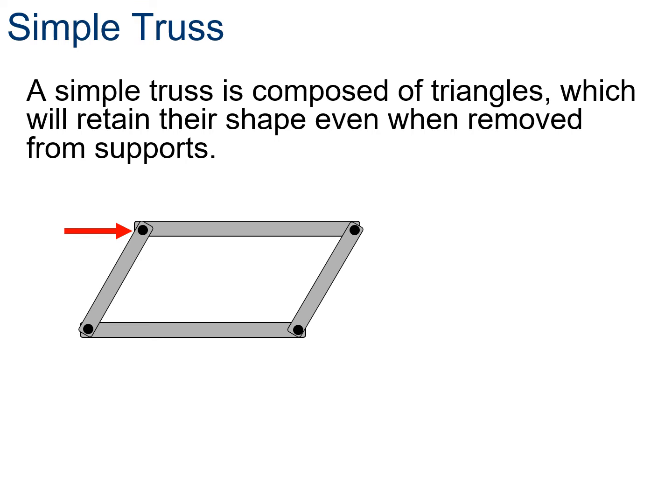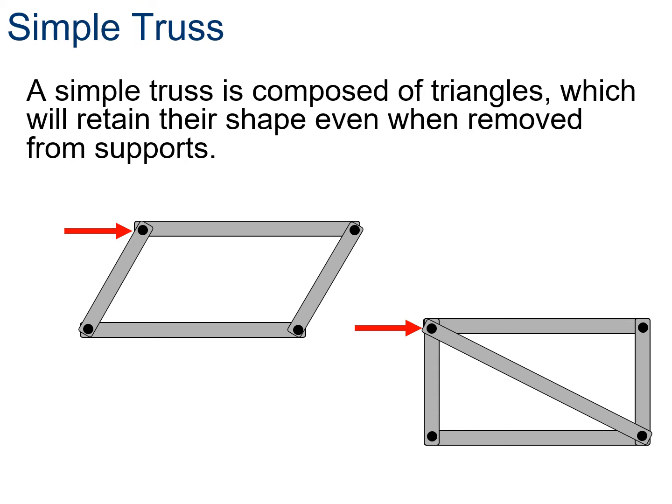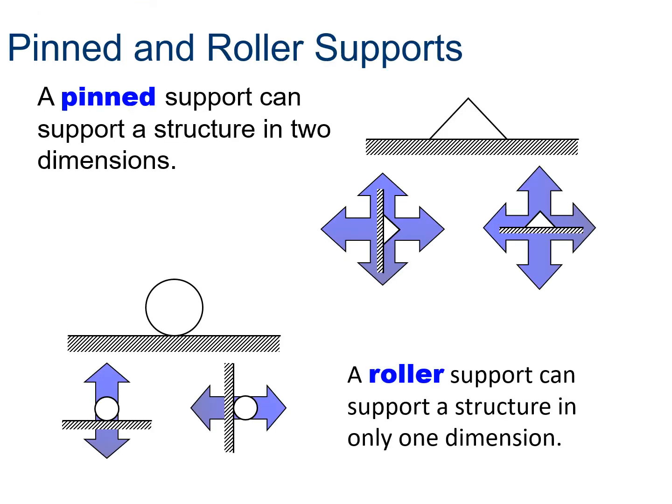So you have to do something else to make sure you prevent any kind of rotation like that or movement. That's really what any static structure does: if you strategically place all of your beams, you can stop any kind of rotation of that structure and continue it to be static, which is what you design buildings and bridges to be. So here what you can do is add a diagonal there, and what that's going to do is allow that force to be applied but nothing to rotate.